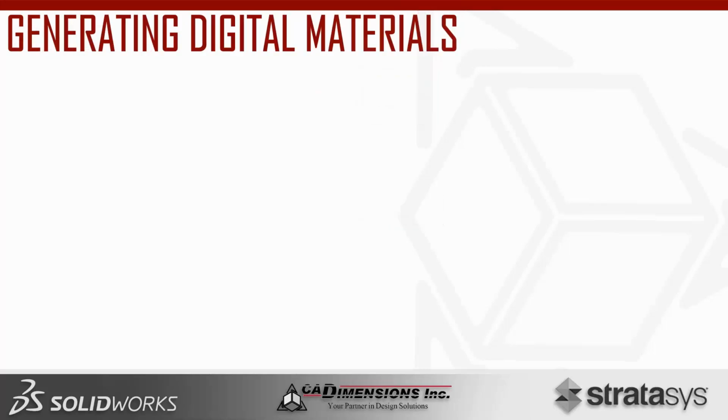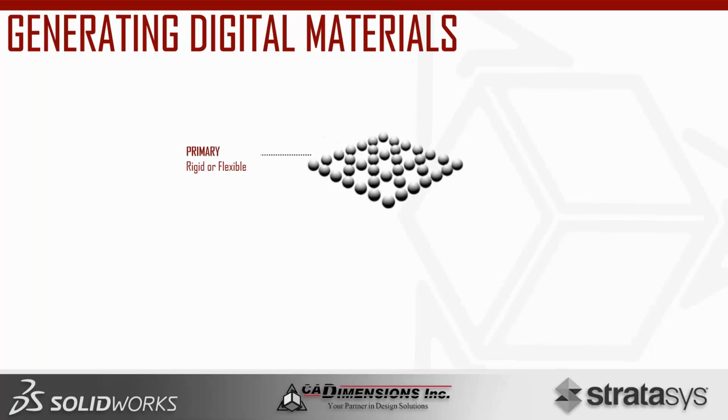Now, a little bit on digital ABS. This is considered digital material. Now, digital material is a term that you see consistently in the realm of PolyJet. We have a graphic here to kind of explain what that means. Essentially, it's combining two or more materials together. And the higher up in the systems you go, the more materials you have at your disposal. Currently up to 6 different material combinations at any given time with the J750.